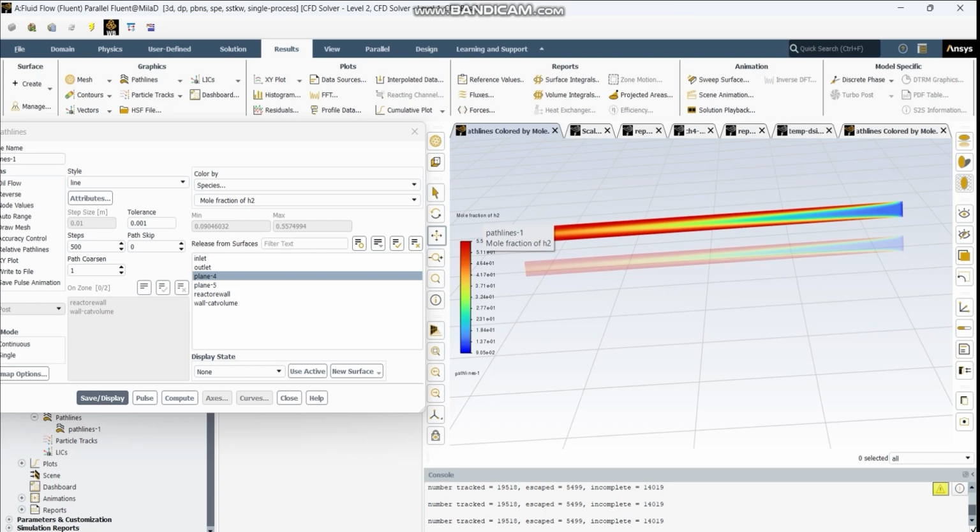Hydrogen generation begins as a steam methane reforming reaction initiates, and it increases progressively through the catalytic zone. The concentration rises gradually, reflecting the conversion of the methane and the steam into carbon monoxide and hydrogen, then further into the carbon dioxide and more hydrogen via the shift reaction.